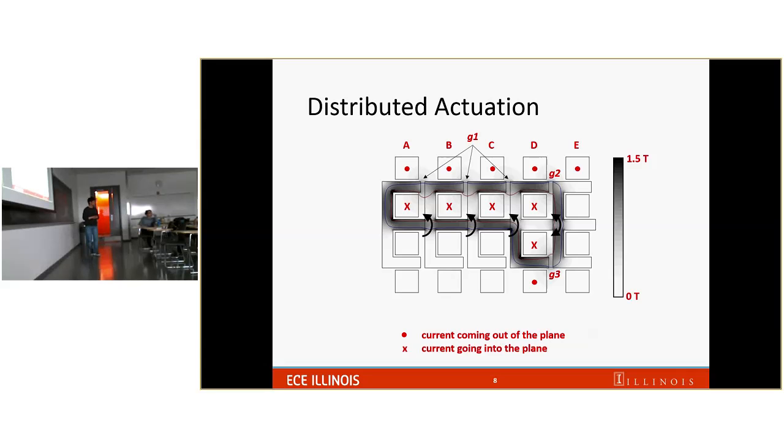Question. In your controls, you use PI controllers, and you have KP and KI. What is the sign of KI and KP? It is positive. All positive. Okay, so you wouldn't see any problem. I'm just curious, have you ever seen, when you make a step command, because you introduce a zero to the system, that at first it goes the opposite way to your command, and then comes back to follow the command? Have you ever seen that? No, I think that never happens in this system because I use positive KP and KI. Okay, thank you.